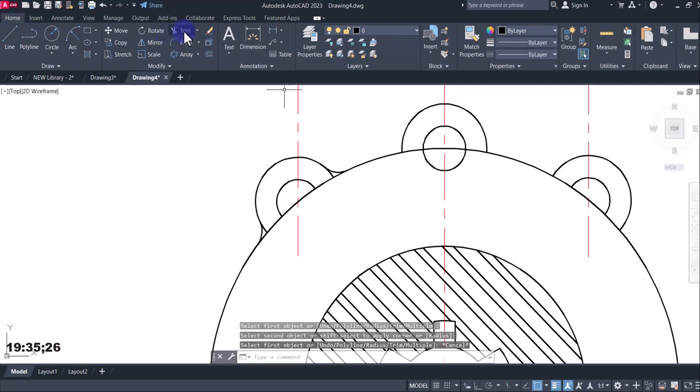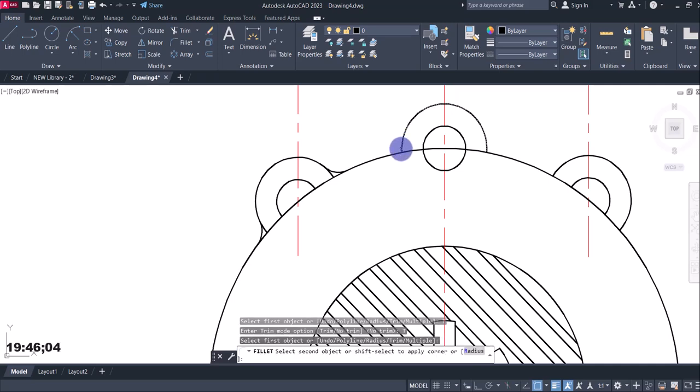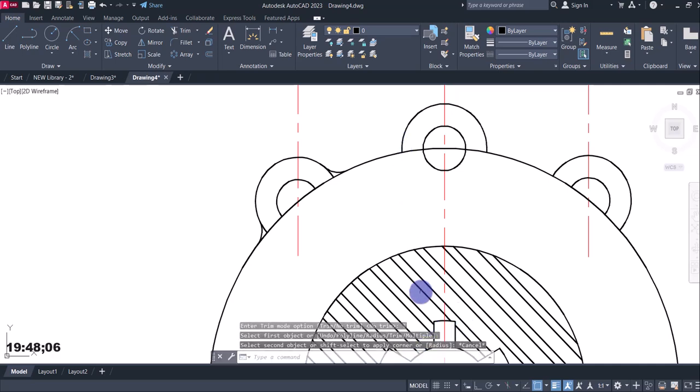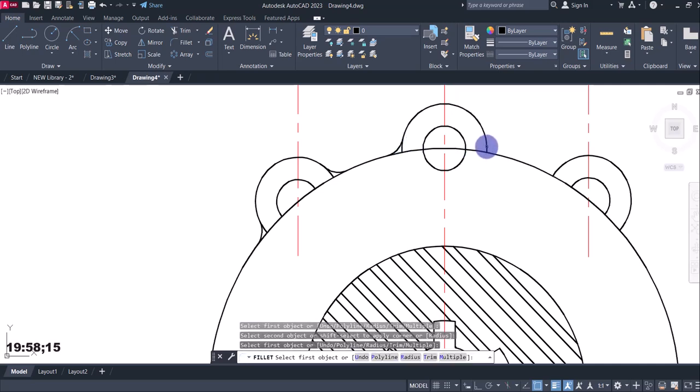Okay, I'm going to be doing the fillet again. This time multiple, trim. I will activate the trim option, because, oh no, I don't want it to trim. Multiple, okay. Trim, I will say no trim. Okay, let me keep applying. So that will give it a nice blend.